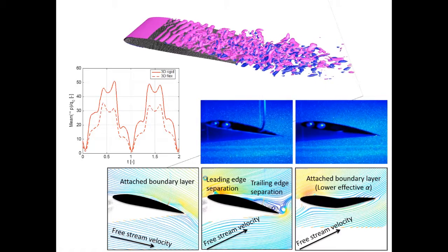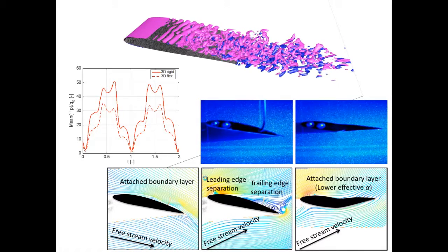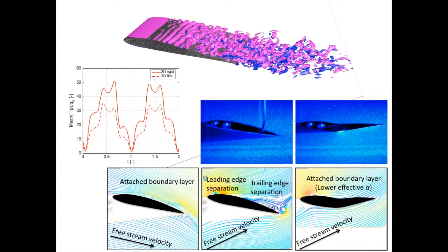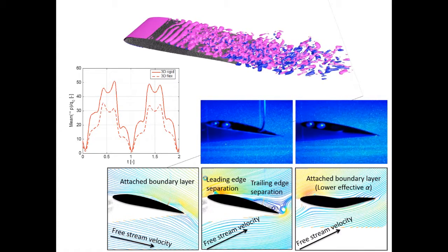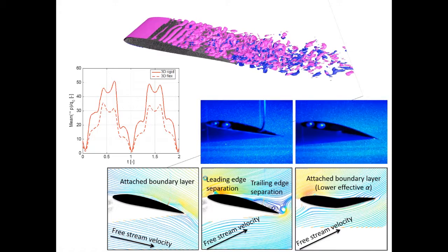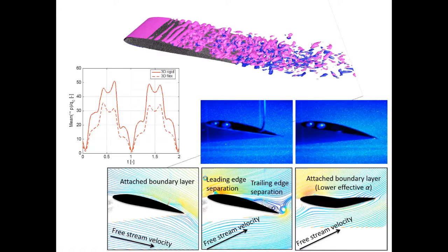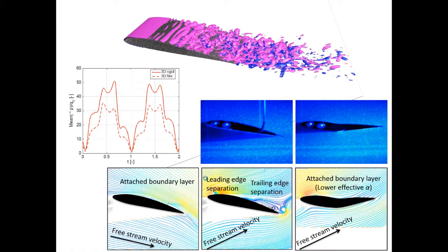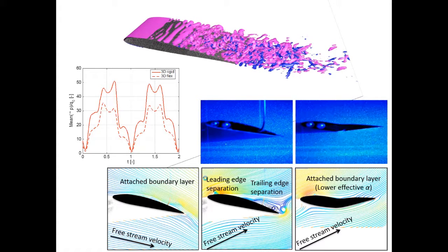What happens, for instance, is that you have these vortices which are generated on the turbine, and these are going to interfere with the vortices which are coming from upstream. Now here you have the blade, and if you move this blade, you can actually try to change these interferences between the two vortices, and you can completely change the flow field.